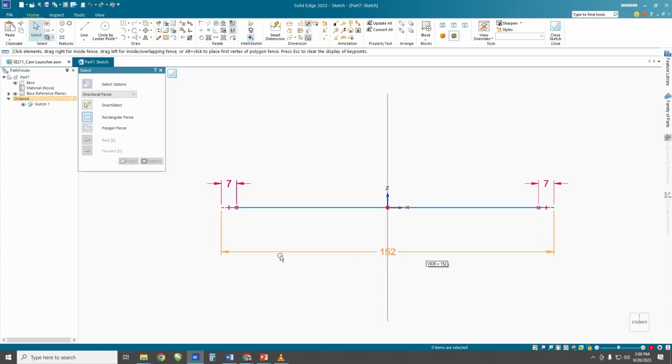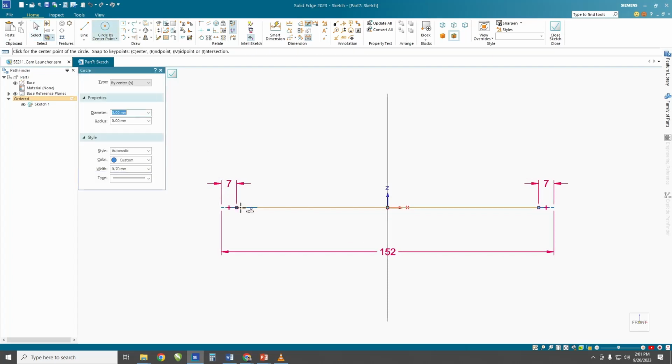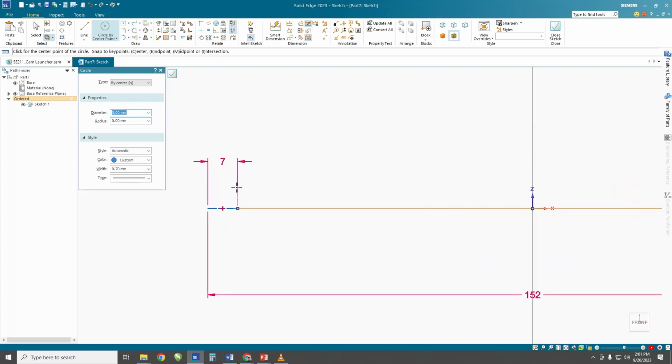Okay, so now that we have our dimensions in here, we want the dimensions in here as well because we're going to be, again, adjusting this length, and I need some variables to grab onto. I don't want it to be able to change willy-nilly. I certainly want these ends to be locked in so that my hook on the end can't get distorted or anything like that when the length changes.